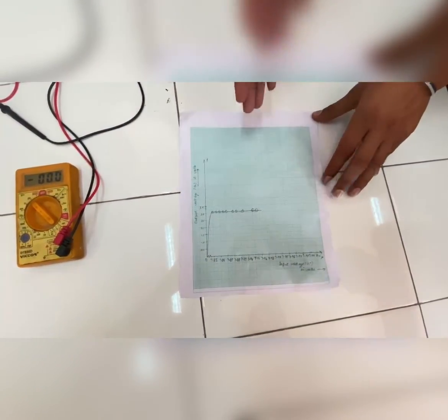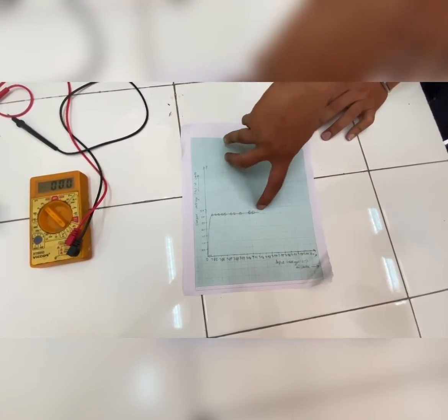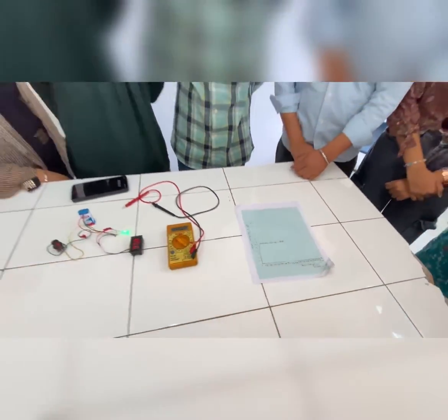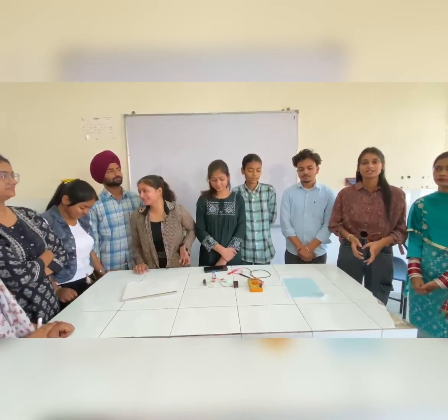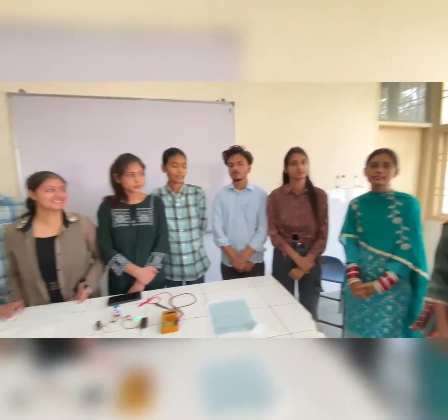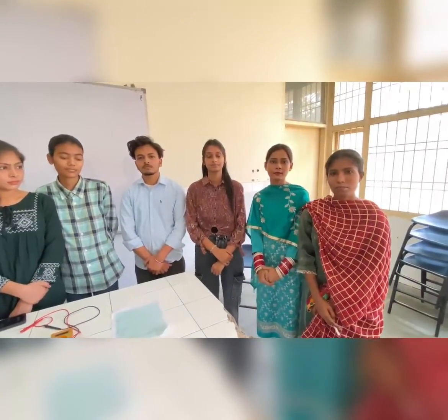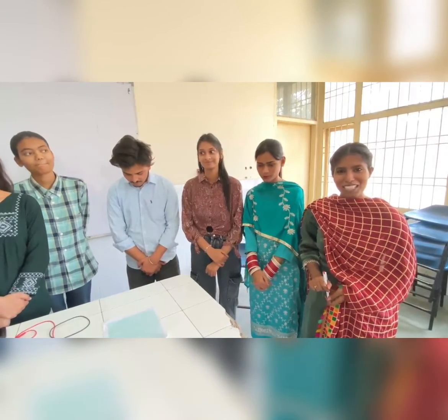The graph shows that the output voltage increases linearly and afterward it becomes constant. There are some advantages of Zener diode like voltage regulation, over voltage protection, switching power, reference element and fast response, etc. There are some disadvantages. It cannot be used for high power.